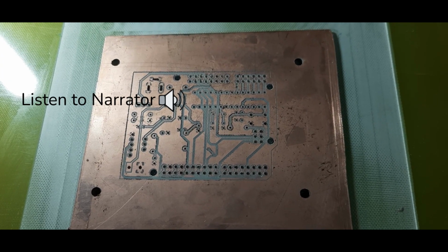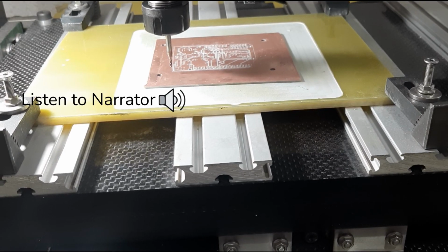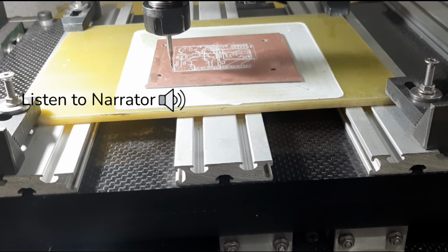End of isolation on the bottom layer. This is where we start using the 2 mm bit to do the cutout. Note the 5 mm tabs which are left after the milling operation.